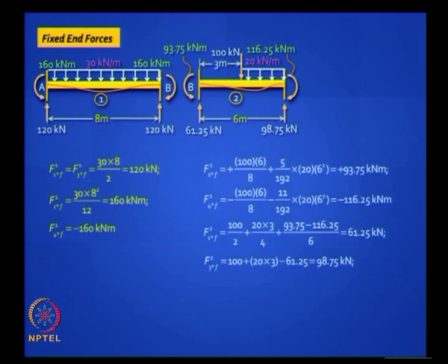And here you have to be careful. You have to first calculate the two fixed end moments as shown here. After you calculate the fixed end moments, you should calculate these reactions, because the reactions are not only an outcome of these directly applied loads, in the sense these shears come not only from direct shears but they also come from moment shears. That means the difference in these two moments will add on to this, so this moment is more than this.